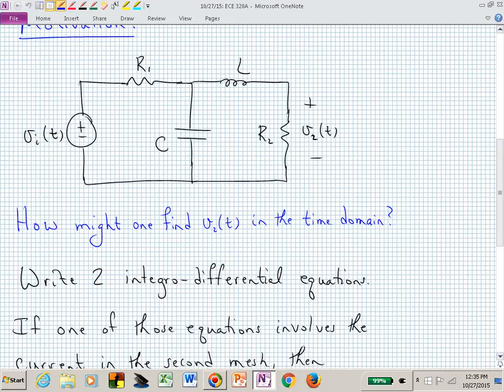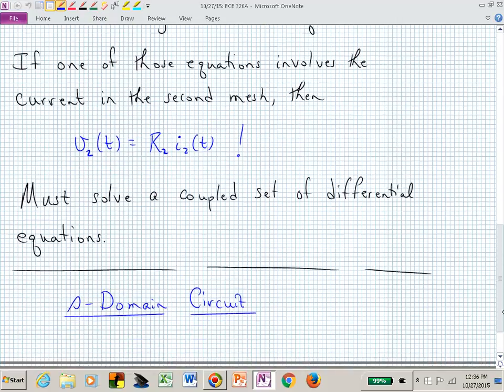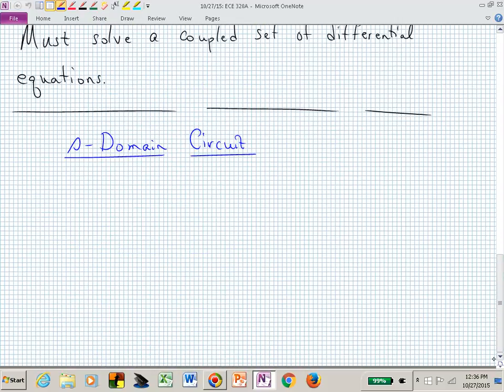Based on what you know today, you can solve that. It's just that now we are going to try to step out of solving differential equations explicitly and essentially do those implicitly by working in the frequency domain directly, and at the end inverse Laplace transforming to get us back into the time domain. What we want to do is rewrite, or draw, that circuit in the S domain